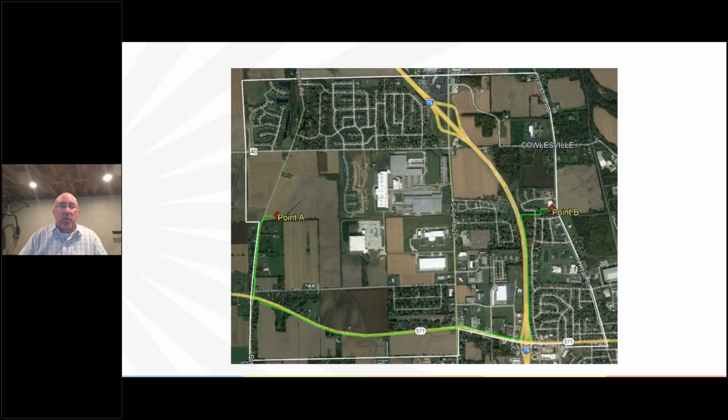So we eliminated the road along the freeway due to the limited access and expected inability to maneuver equipment near the sound wall. Also would have needed to go through subdivisions. So at the north end, we could have had an access just to the east or west of point B, but that access would have gone through a residential neighborhood.